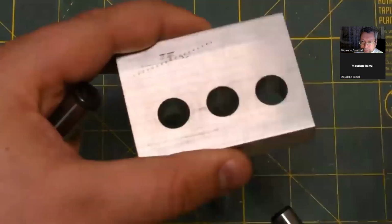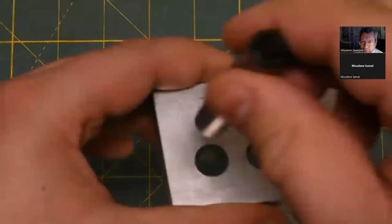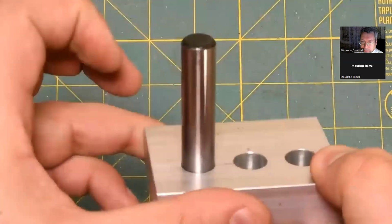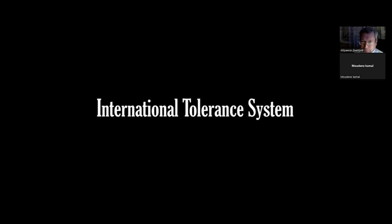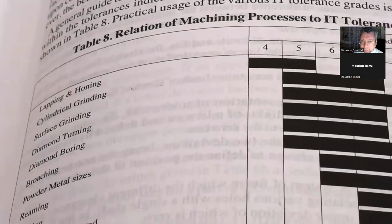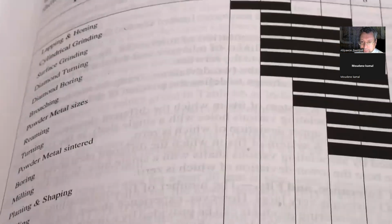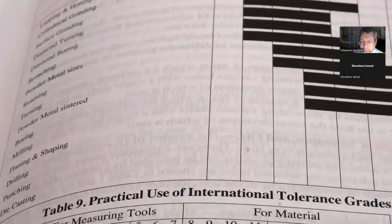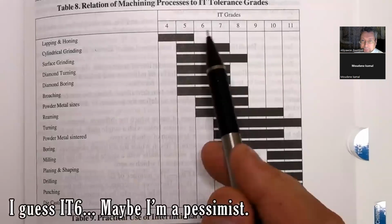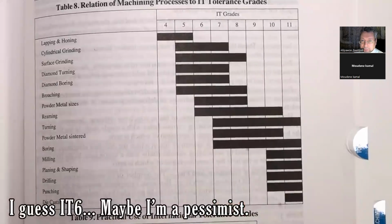Note how they fall through the holes at different speeds due to the minute differences in the clearance. The numbers themselves are actually determined by the IT system, the International Tolerance System. Every manufacturing process can be statistically analyzed and an IT number can be determined. This means that if I'm reaming a hole, I can look up the reaming process and see that at best I can achieve about an IT7. So I can't specify an H5 or a G5 hole if it's going to be reamed.